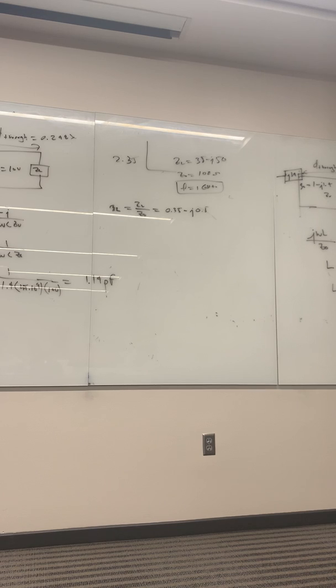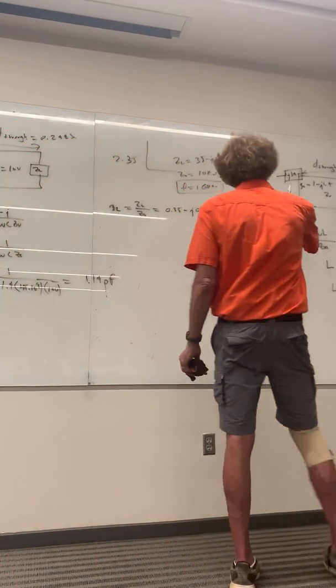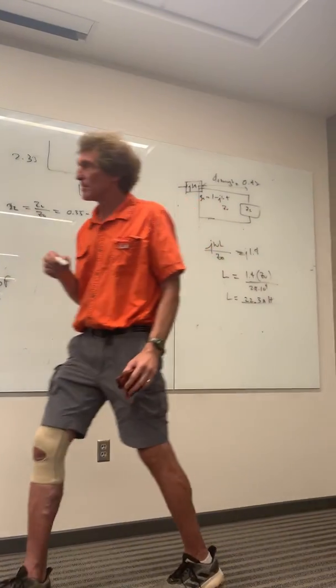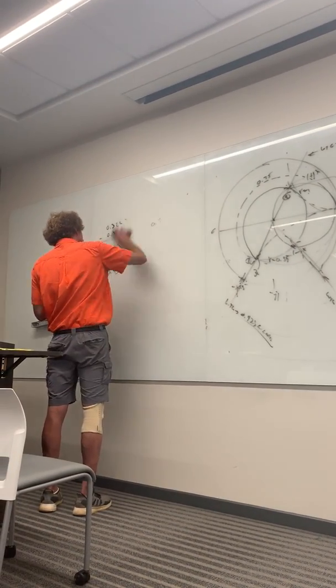Well, that's high frequency engineering. We had to use plastic screwdrivers and all sorts of other things, because where our hands got near, the frequency changed on a lot of this stuff, the oscillators. It was a nightmare. Now, the way you get around that is what we actually do, and I'm going to show you this now. Instead of using elements, capacitors and inductors, and sticking them in there, we stick pieces of transmission line in there.